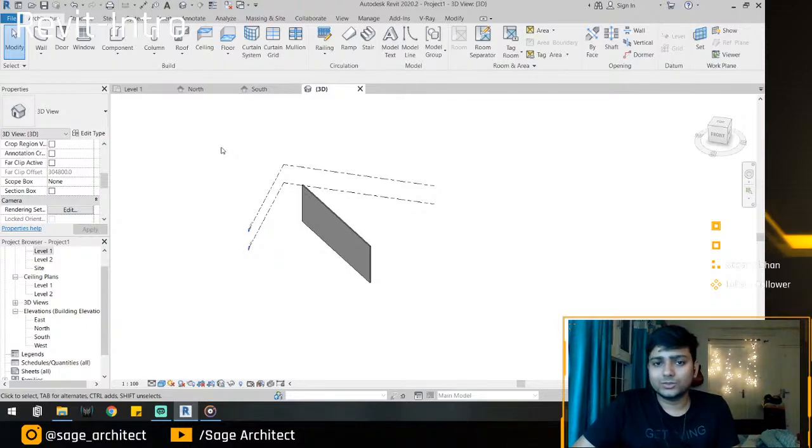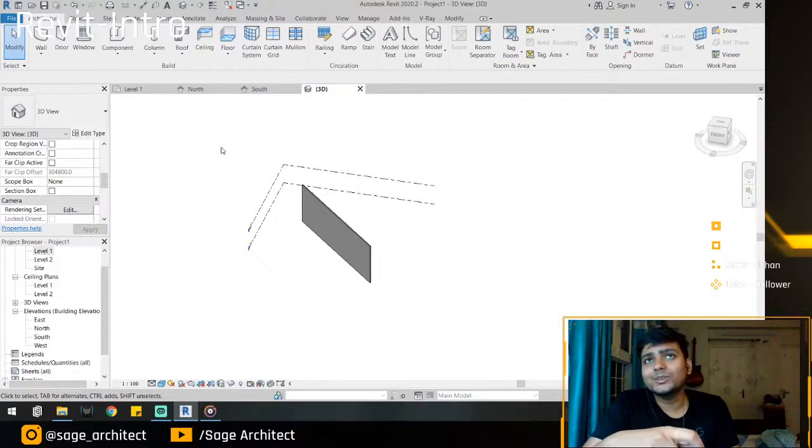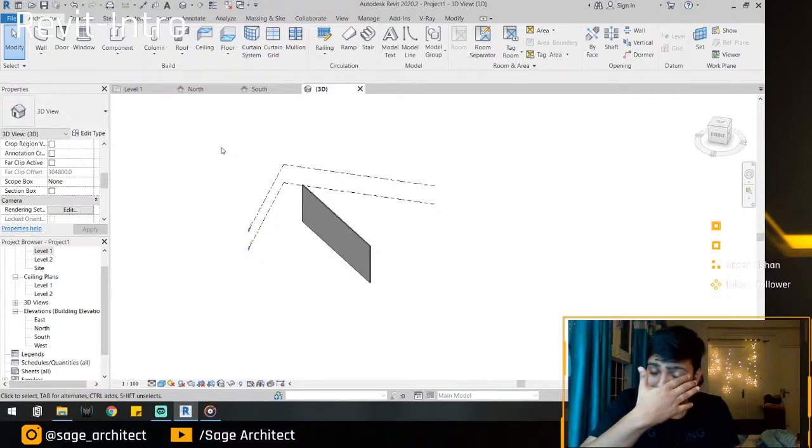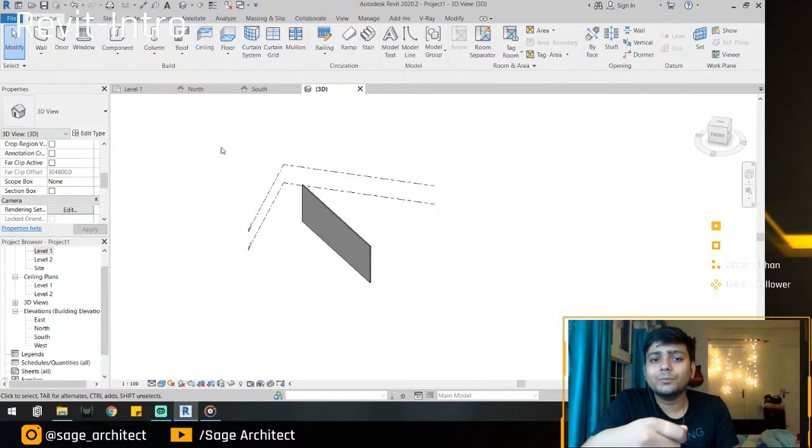Revit is a very heavy software, let me tell you, but you can make a model in an i3 also, or in an i5 also. You can make an entire apartment in an i5. You just have to know the tips and tricks. So you can make the model as light as possible while doing what you want to do in the model. You can create links, groups, and components and copy them, so the project weight is lighter.